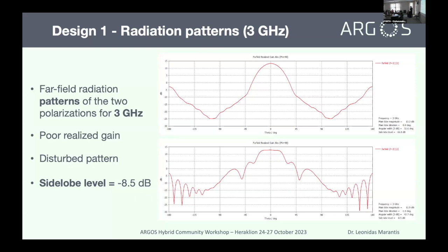So far in our simulations, it's just a perfect surface for the reflector with no roughness. Because if we apply roughness, like 1, 2, 3 millimeters, at the surface of the reflector, this is going to be a huge problem for us in CST, in the electromagnetic solver, with the number of the cells.